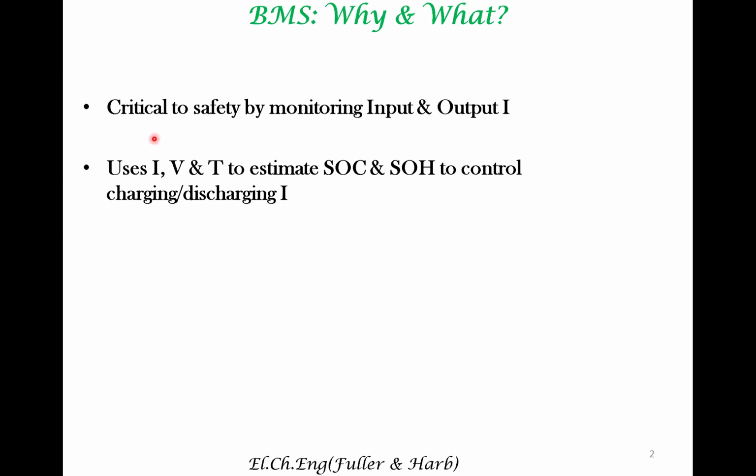It uses this information, the voltage information, and the temperature of the battery to estimate the state of charge and state of health of the battery to control the charging and discharging current.